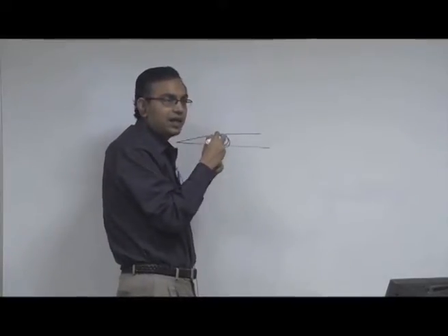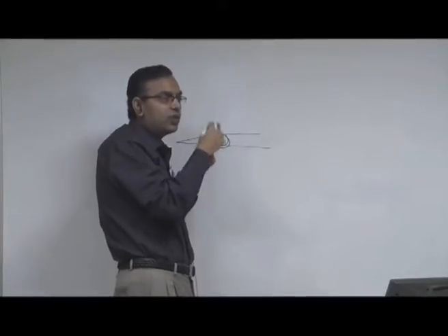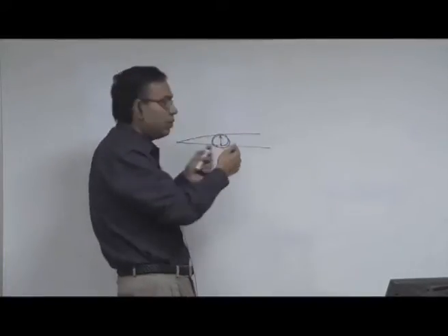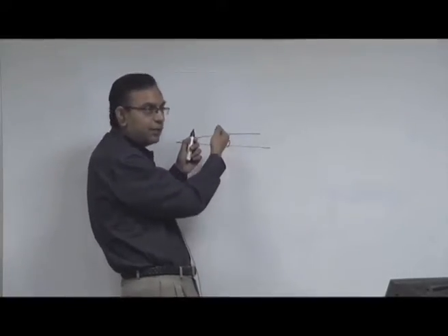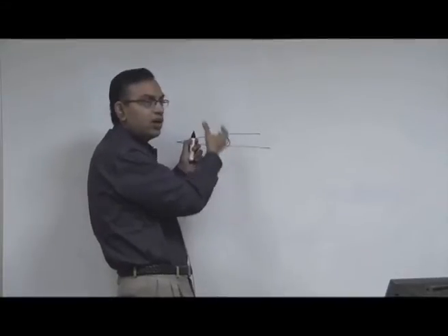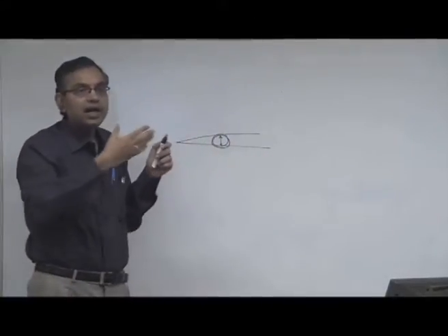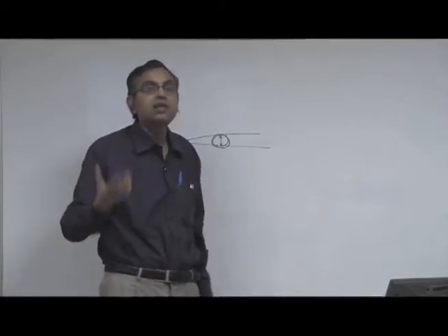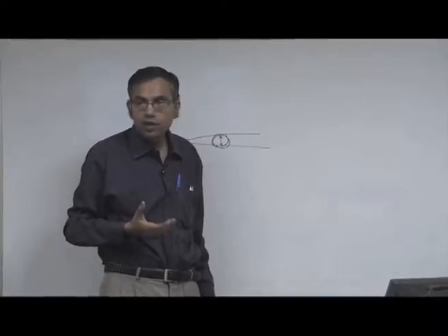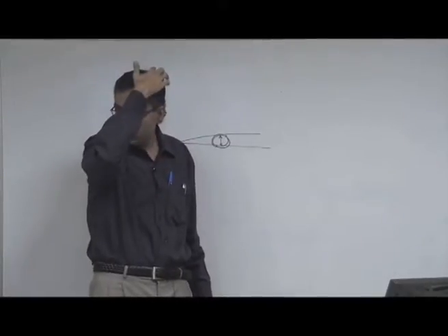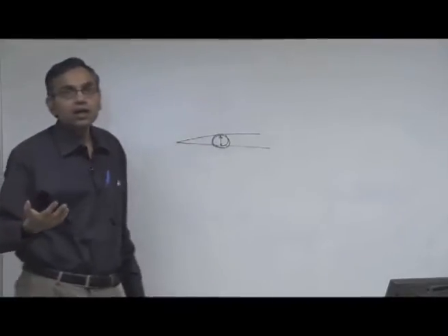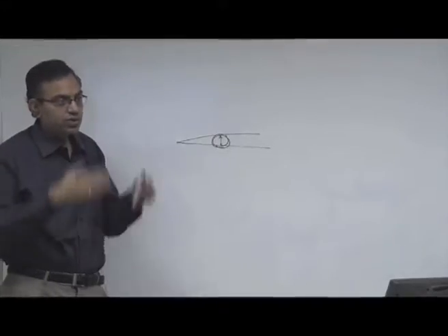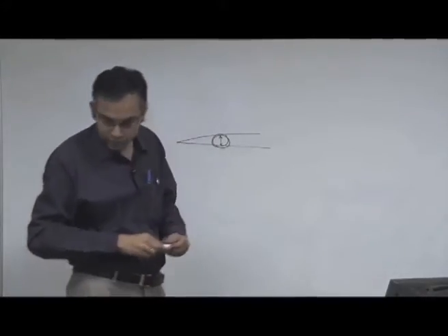So, that kind of perturbation where you treat this differently is called a singular perturbation, and the whole idea is that, physically try to understand that this is a small region. So, to make it prominent, you try to apply a transformation so that this small region is magnified, as if you have a magnifying glass. By putting a magnifying glass, you have magnified or stretched the boundary layer region and have applied a transformation to achieve that stretching. This is called a stretching transformation. Okay. So, this singular perturbation theory is commonly used to analyze the boundary layer type of flows. So, singular perturbation is also important.